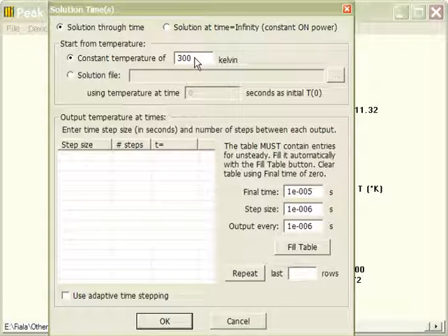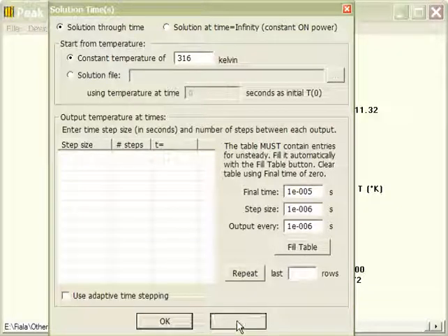And here we would compute a steady state solution at full on power, and then take 1/3 of the temperature difference between the peak temperature in the solder layer and the backside to get the approximate temperature difference across the shim. Now this is not going to be as good as using the starting solution that had the whole temperature distribution as initial condition, but it should help us get closer to the final solution.